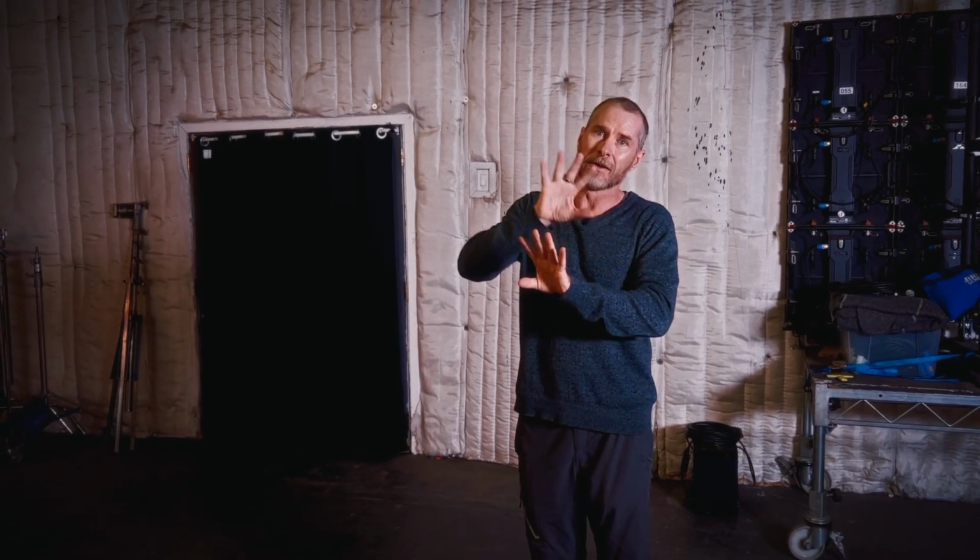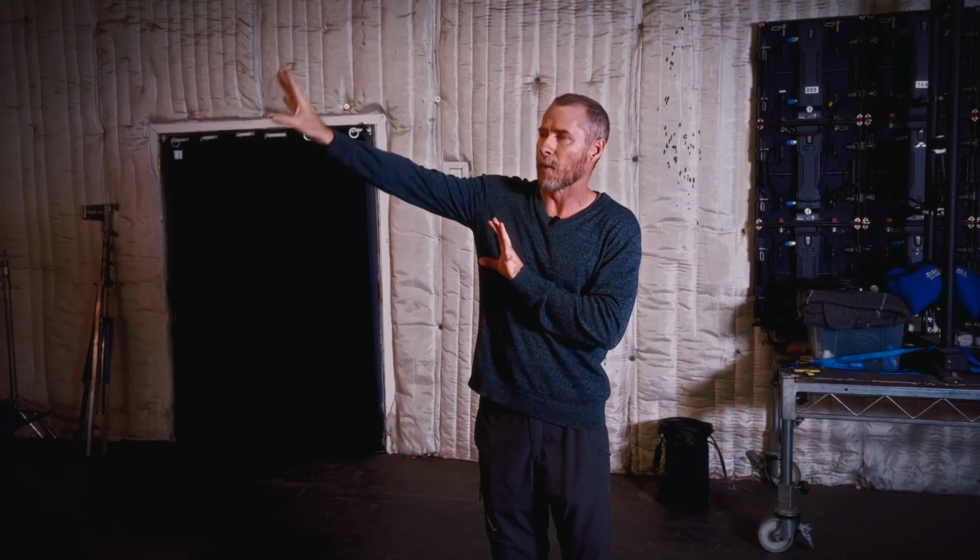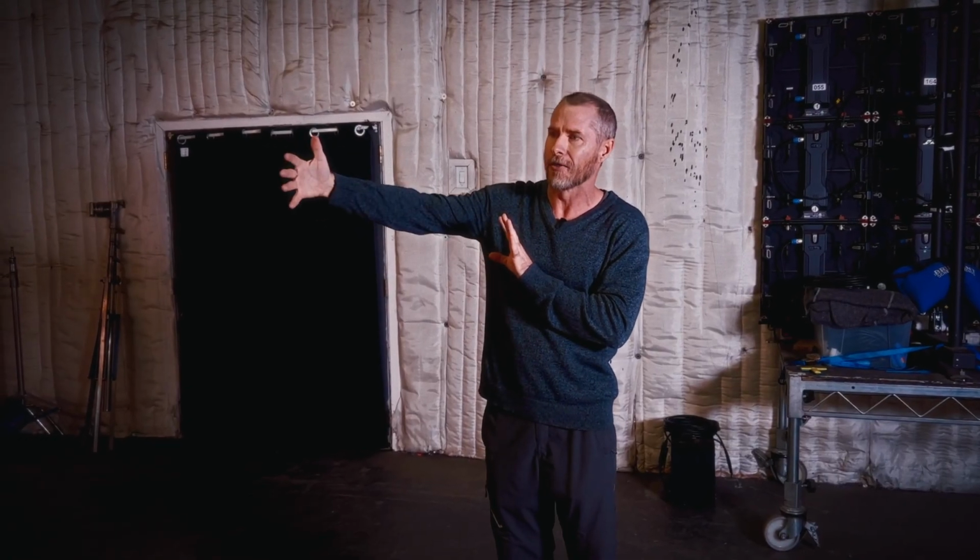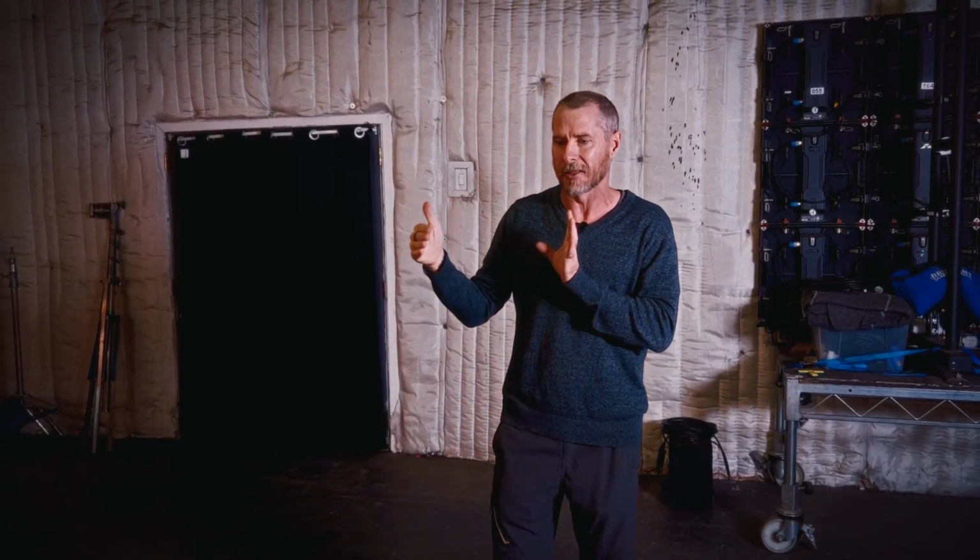And then it's constantly communicating with the computer to tell Unreal Engine, hey, this is where I am. So then Unreal Engine has the mirrored virtual camera inside the software that we looked at, and it adjusts that. And so it knows, okay, from this place, this is what we should be seeing and how far the depth of field should be based on the lens, because you also have to calibrate your lenses and let Unreal Engine know.